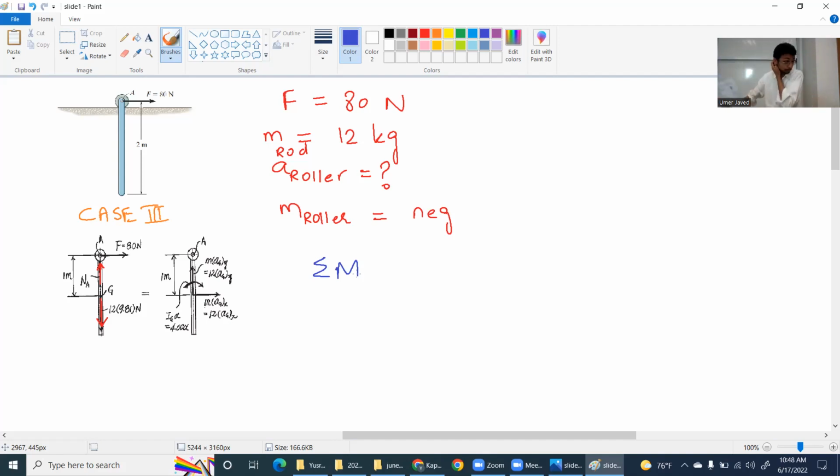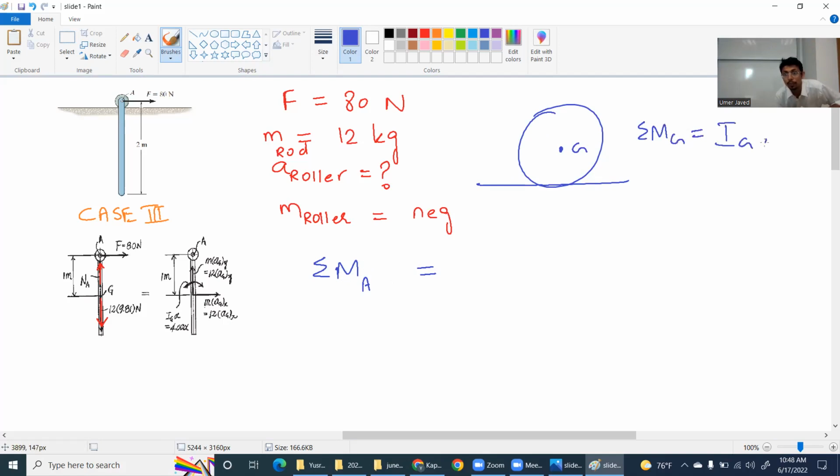We always do that. So there are no qualms that I will write this. If a student had tried to solve this question by the no slip condition, that would again be correct, because a no slip condition means the point A has zero velocity.